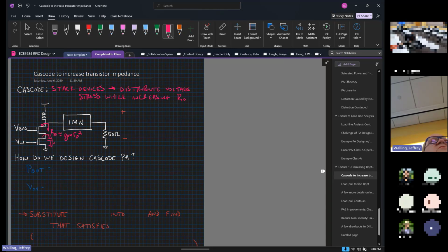Also increase noise. Is the top transistor in triode? So I should be careful. I'm probably not going to use that device in triode for a linear amplifier. I'm going to do that if it's switching. So yeah, we have to be a little bit careful there.